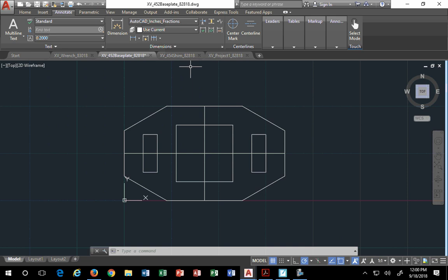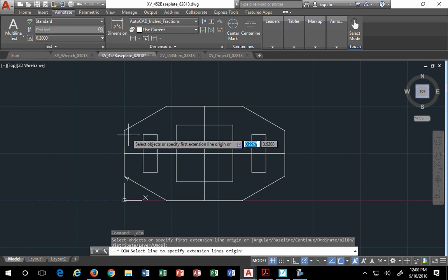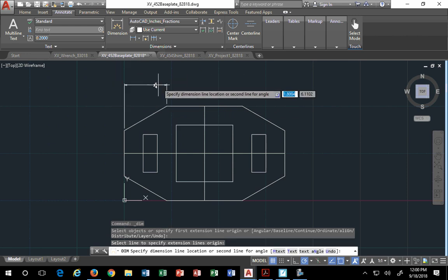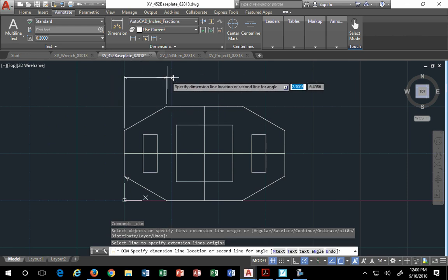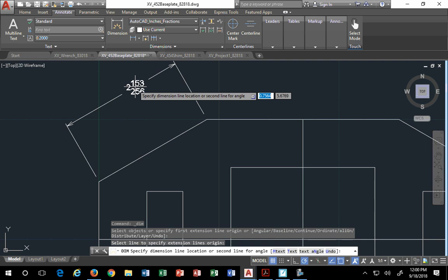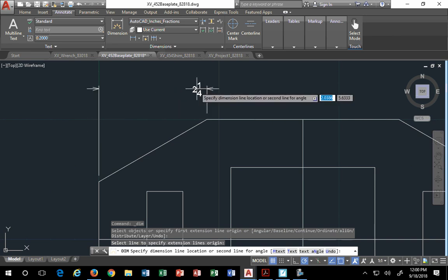There's multiple ways to detail a drawing as far as setting up your first dimension. You can actually just go ahead and pick linear. You can use the Smart tool. If you use the Smart tool, you actually pick a line, and then it wants to dimension it somehow. Now you'll notice when it's at an angle, remember I'd set it to a fraction of 1 over 256? Well, that's the fractional value at the hypotenuse of that triangle, when you think about it. And here it is at this dimension, 2 1/4. So whatever the lowest fractional value is, that's the fraction you'll see.